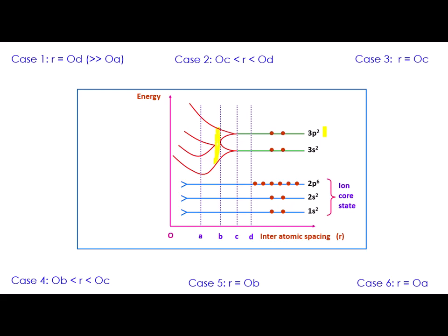That means these 4n energy levels of the p orbital are vacant or empty, whereas the 4n energy levels of the s and p orbitals are filled. Now, all these 8n energy levels are merged with each other, and out of those 8n, 4n energy levels are filled and 4n energy levels are empty.